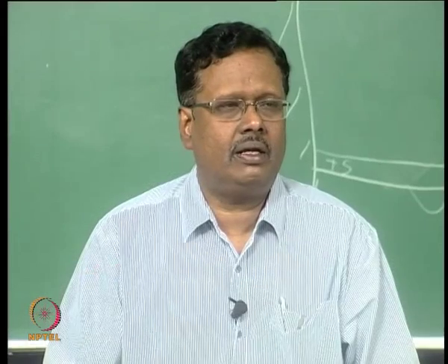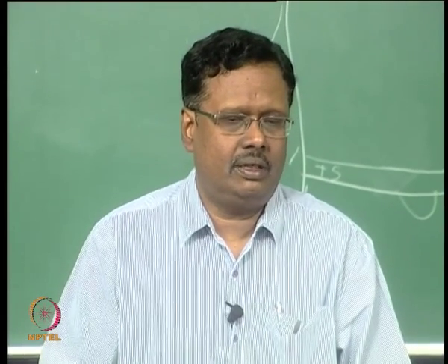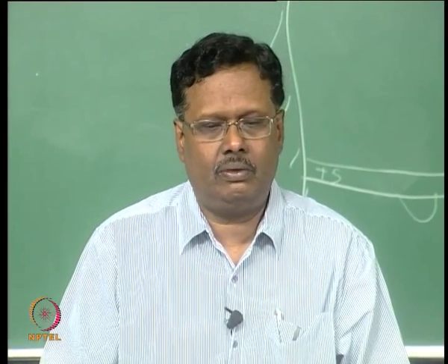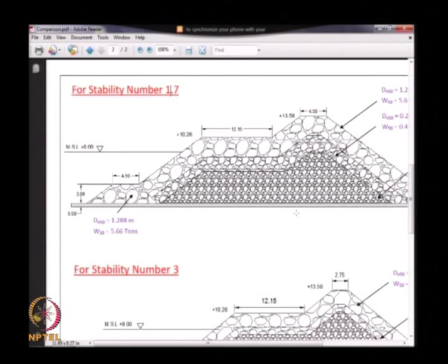It can be the same or it can be different also. Generally we provide the same, but generally the slope above the berm is flatter compared to the slope below the berm, because the wave energy is concentrated only in the top region, not in the bottom region.